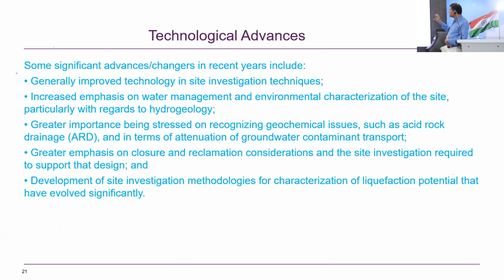And we have to put great emphasis on the closure. That is how the GISTM is now focusing. Each tailings dam's closure should be designed in the beginning. Though we will do that at the end, in the beginning we should have a clear concept of how we will close it.